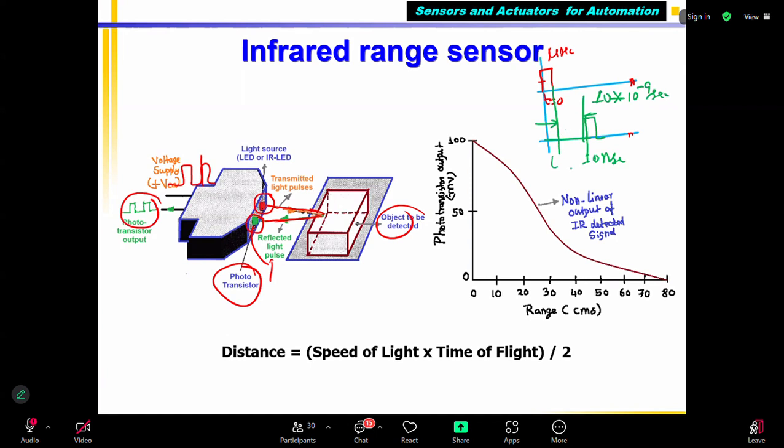It receives. Now, this time is the difference. So what is the difference? I call this T1. This is the pulse when it returns, called T2. T2 minus T1 is called capital T, which is called the time of flight. Note it down. What is flying? The light pulse traveled from here to the object, hit the object, reflected back and was captured. So the light pulse has traveled.